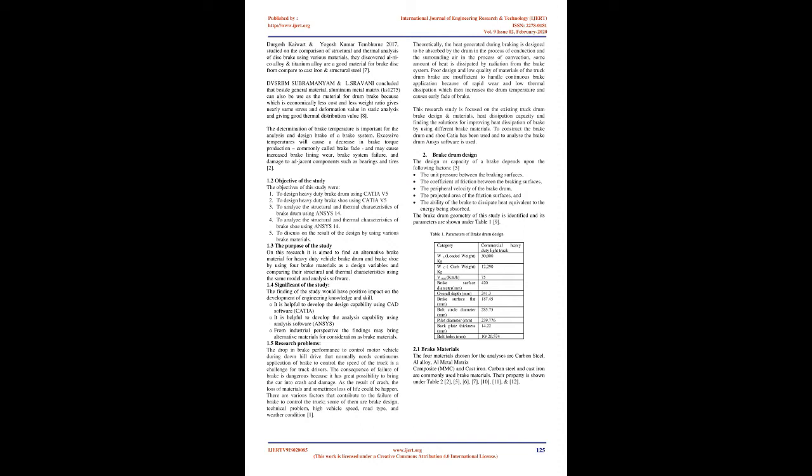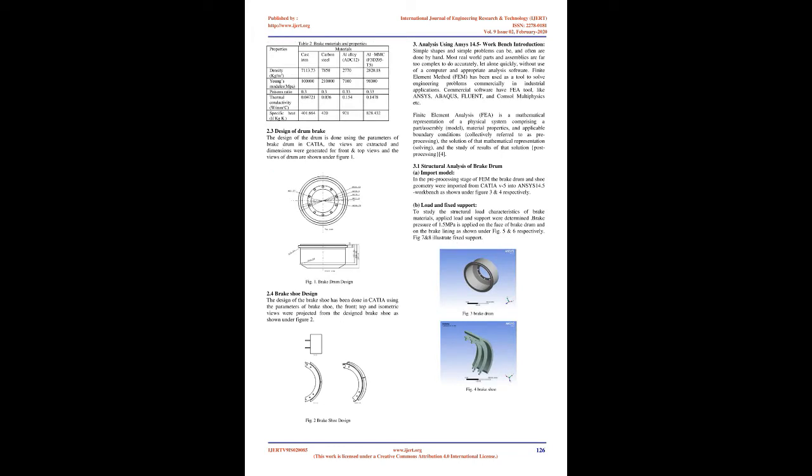1.1 Background of the study. Brake is a control mechanism mounted on a vehicle to control the speed of the vehicle by applying brake pressure at the road wheel. Depending on the type of operation, brakes can be classified into hydraulic, pneumatic, hydropneumatic, and electric. In the case of pneumatic brake, commonly used on trucks, the pedal force applied by the driver on the brake pedal opens the brake valve to allow compressed air to pass into the brake chamber and turns the camshaft to actuate the brake shoe/pad against the rotating drum.